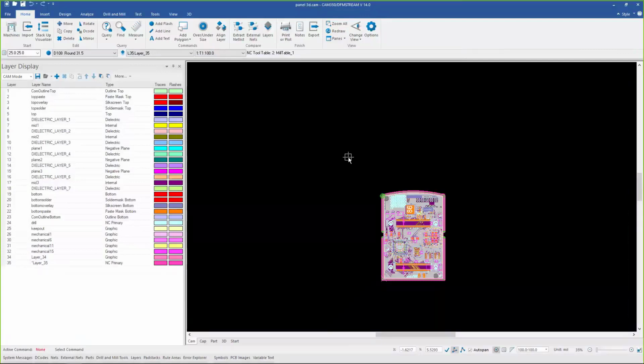What the design analyzer does is basically it goes in and, let's just say spacing, for instance, trace-to-trace spacing. It goes through the design and looks for the smallest instance of trace-to-trace spacing, and that's the number that it puts in there. Same idea with trace to pad or annular ring or copper to hole barrel. It extracts that information from the graphics, if you will. It's not just pulling straight out of a Gerber file, and really that information isn't in a Gerber file. It has to go out and look at the graphics and find that information, and that's how it's extracting those minimums.